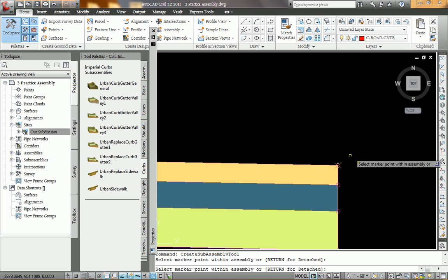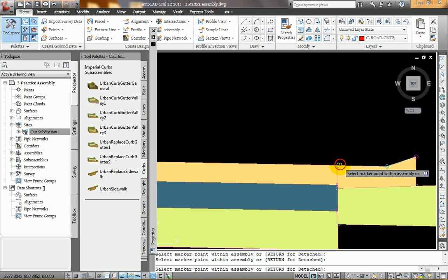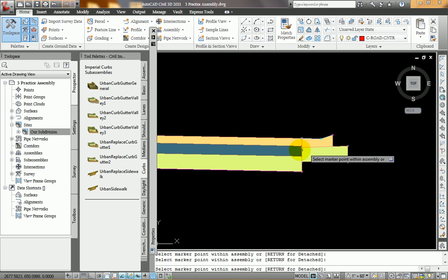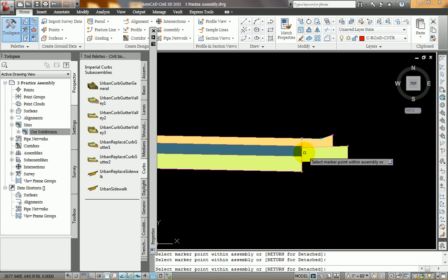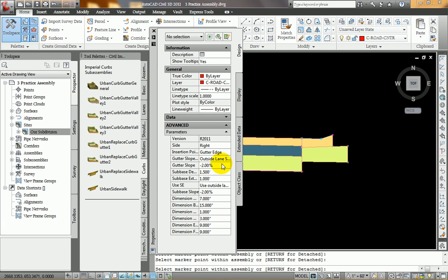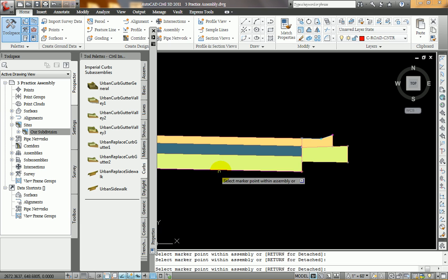Whenever we zoom in here, we click this upper left-hand corner, and you'll see that the sub base here is way higher than the sub base over here, and we want them to line up. If you go back into properties for the sub base depth, we had a 6-inch and then an 8-inch for our top 2 layers. That's a total of 14 inches, which is 1.167 feet.